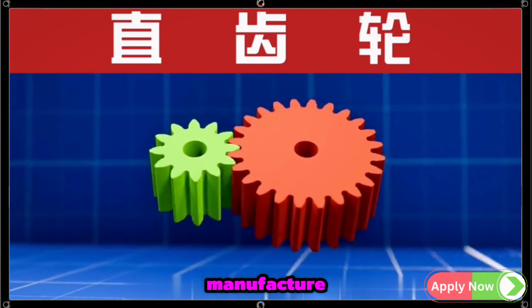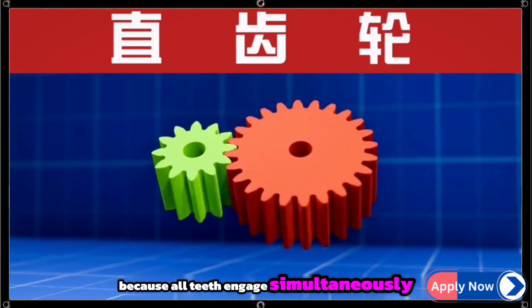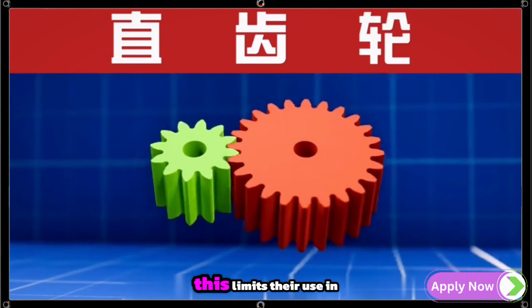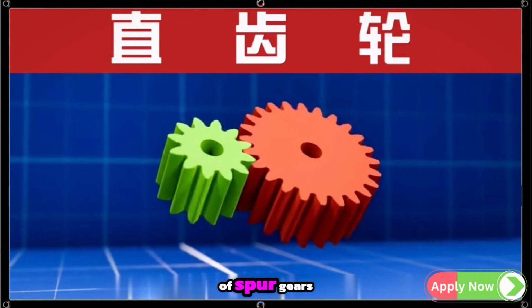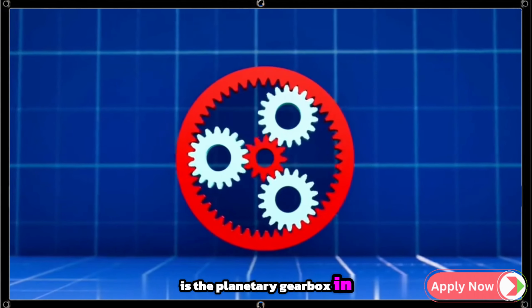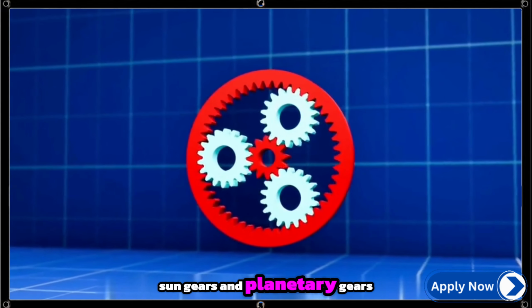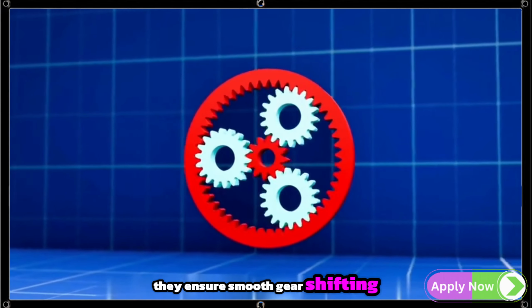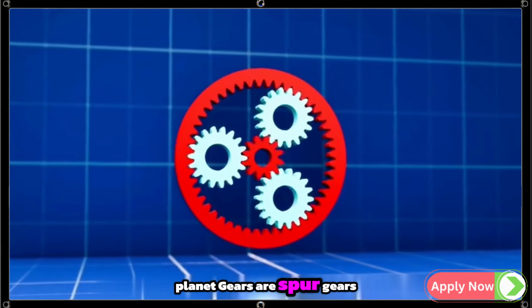They're efficient and easy to manufacture, but they can be noisy, because all teeth engage simultaneously, creating harsh sounds. This limits their use in high-speed applications. A great real-world example of spur gears is the planetary gearbox in automatic transmissions. Due to their clever arrangement of central sun gears and planetary gears, they ensure smooth gear shifting. In a planetary gearbox, both the sun gear and planet gears are spur gears.